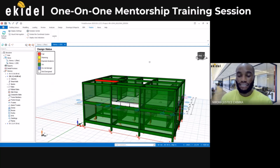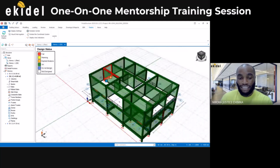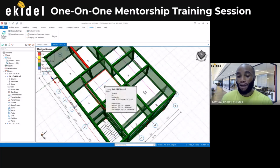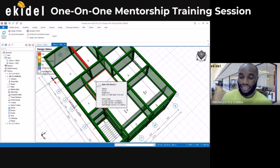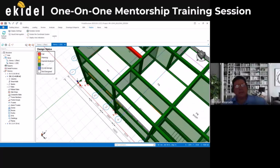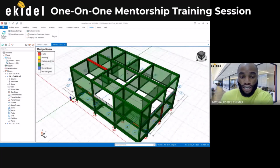So you can see under this chart, all this color coding here: red means failure, yellow means warning, orange means expert analysis, green means okay, and so on. White means not designed. We have not yet designed the slab, but we have already performed the slab work, and we've already transferred the load to the beams, but we did not design the slab to know the reinforcement for it. That's why it is showing white. White means not designed. Exactly. So you can see that most of our beams here are failing.